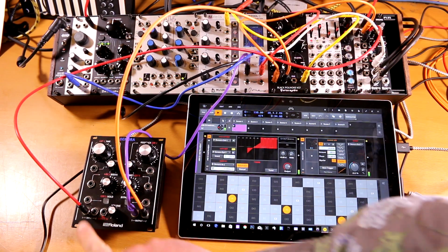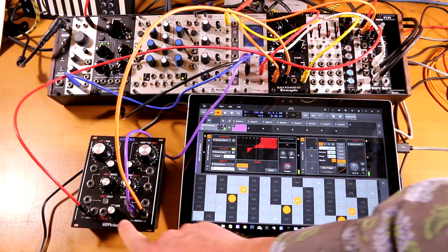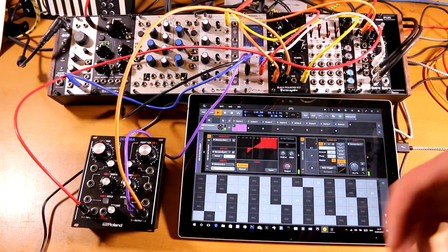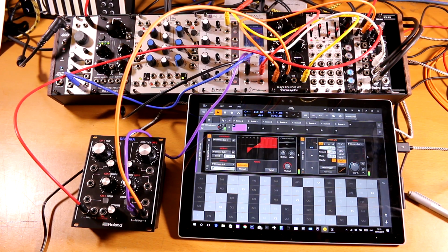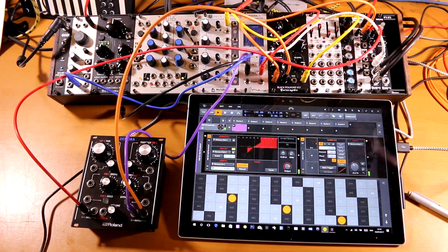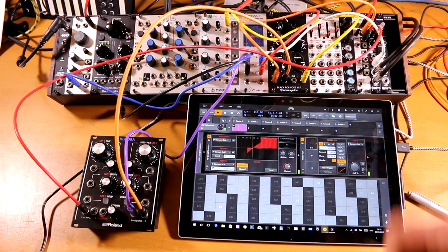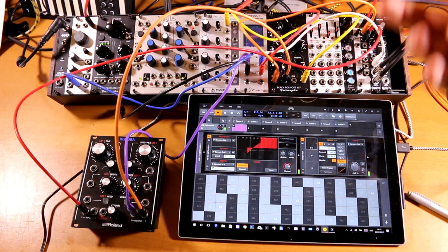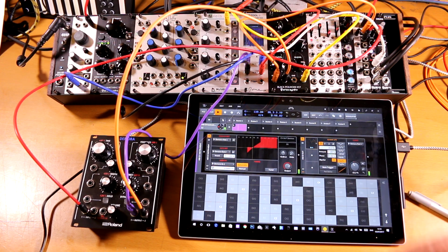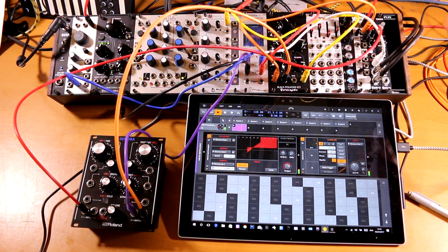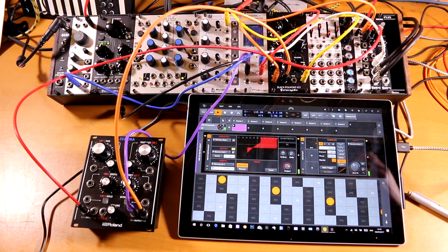So even with the slight weirdness going on between the input and the output, it's still functioning, it still works, because CV is so manipulable, it's so resilient to things. With MIDI, if something goes wrong, it's all just pear-shaped, but with CV, you can get stuff out of it even when it's not really working properly, because you're still interpreting those voltages and it's all analog stuff going on. It's all a matter of degree of working as opposed to whether it works or doesn't.